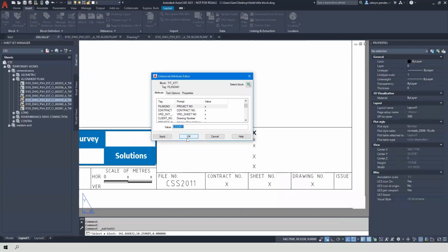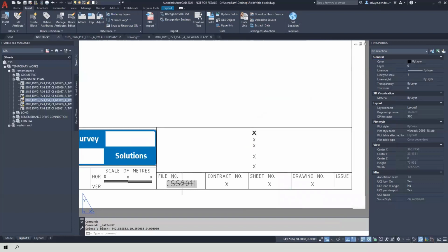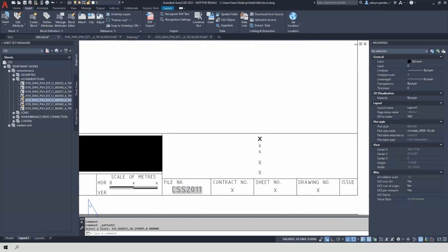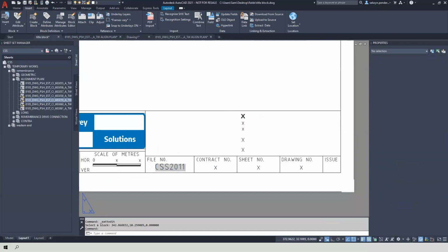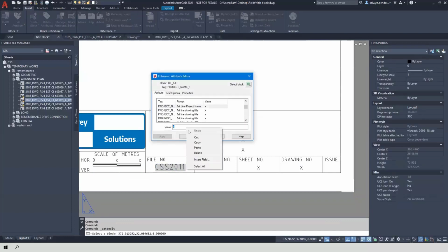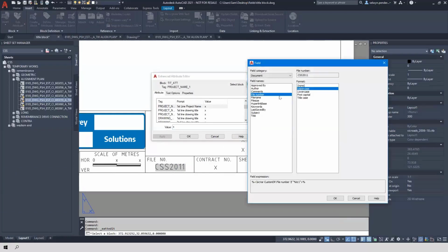Okay, and that field's been associated there. If I go to this one here, double click on that entry, right click, insert field, and this one, it was title, uppercase. So if you recall before, I had mixed case for things, so I can actually change it to be title case, first capital, uppercase, or lowercase.